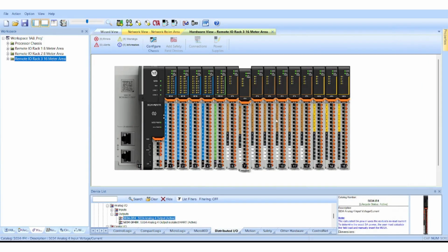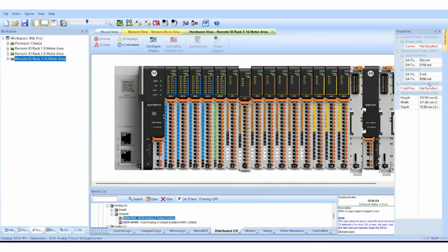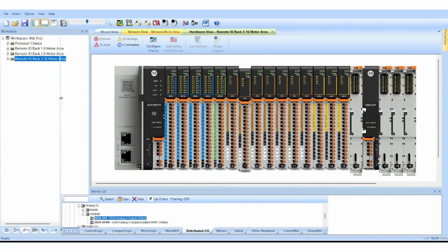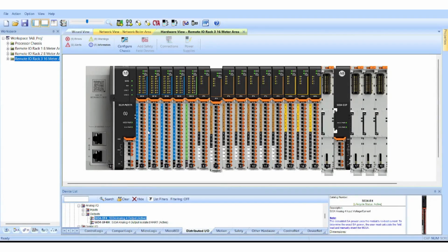The overall network extends across approximately 500 meters, although the individual point-to-point connections between the network switches are maintained below approximately 150 meters. For this communication backbone, we selected managed Ethernet switches interconnected using 1 gigabit per second multimode fiber optic links. There are several reasons for using fiber in this application.